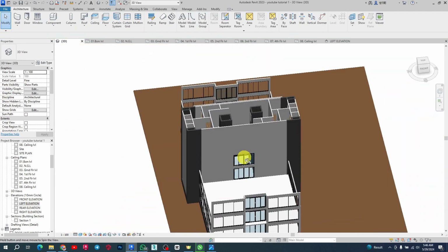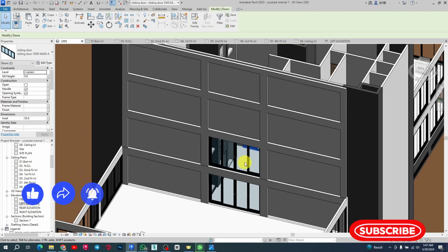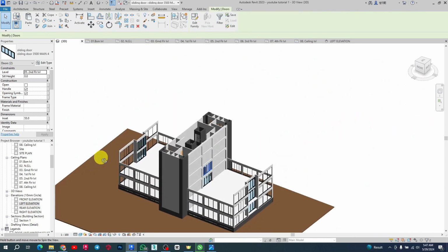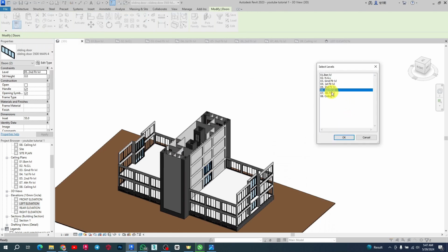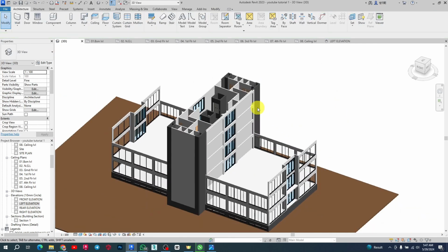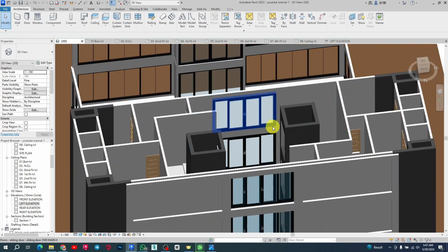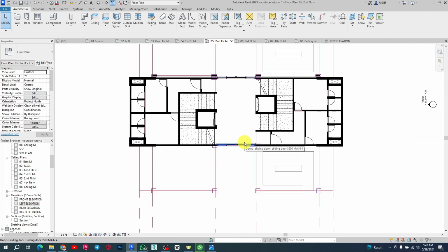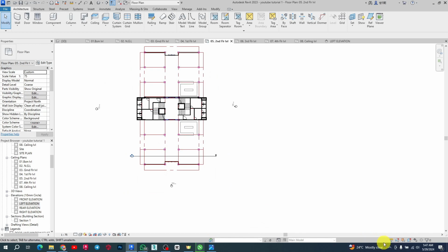I think it's nice. Okay, we might have to copy this door too, and just add this sliding door. So let me just copy one and copy the other one this way. So all the two of them are copied. So copy this and then go to align to third, and fourth floor. So we have it aligning to this other floor automatically, and then covering the position of our restroom. So we'll do the same for the slab. Let me go to the second floor right now and add this extension, right? And that will be it for this tutorial.